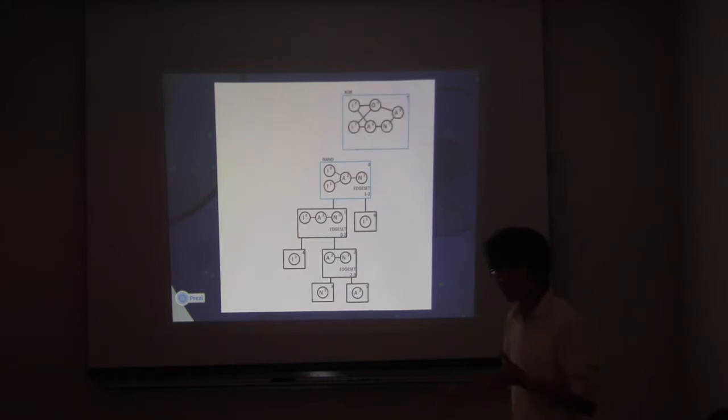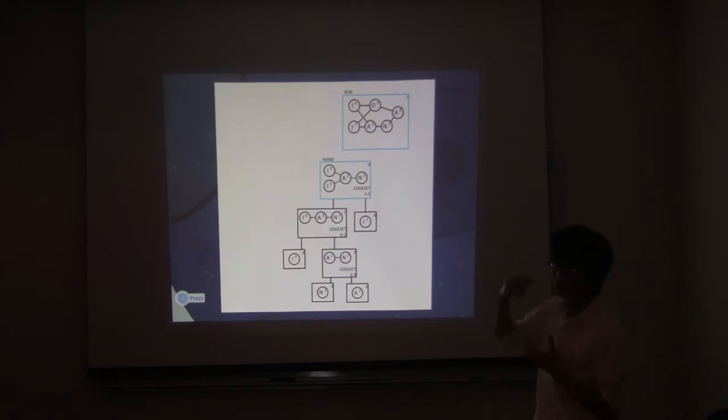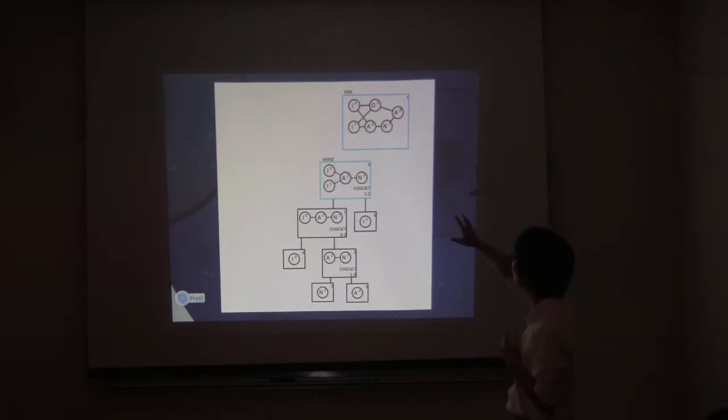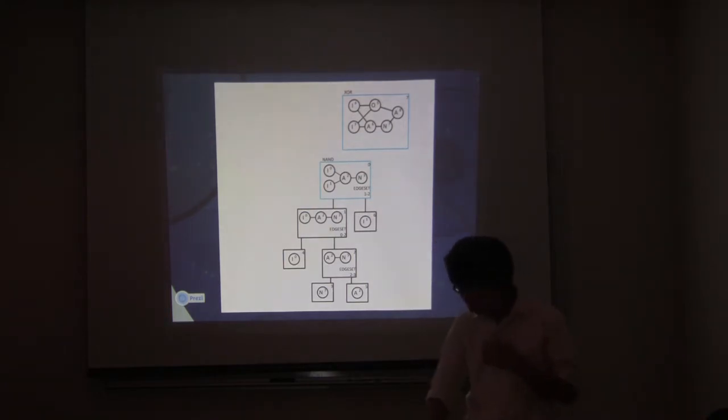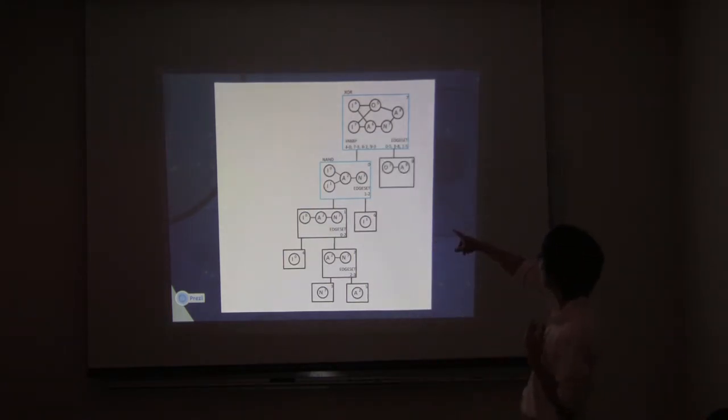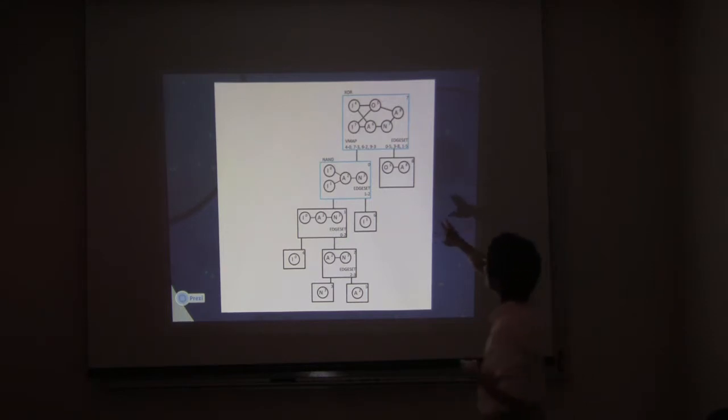So furthermore, this is an incremental process. So any additional pattern that is added into the database, the entire decomposition tree does not have to be redecomposed. So the idea here now is that if we try and add the XOR gate into the decomposition tree, we want to see if there are similar substructures already present in the decomposition tree that we can reuse. So in this case, we can see that a NAND gate exists in the XOR gate right near the bottom. So we use that similar substructure, we map it to the NAND gate here, and then we take the difference between the current circuit and the NAND gate, and we get left with this one right here.